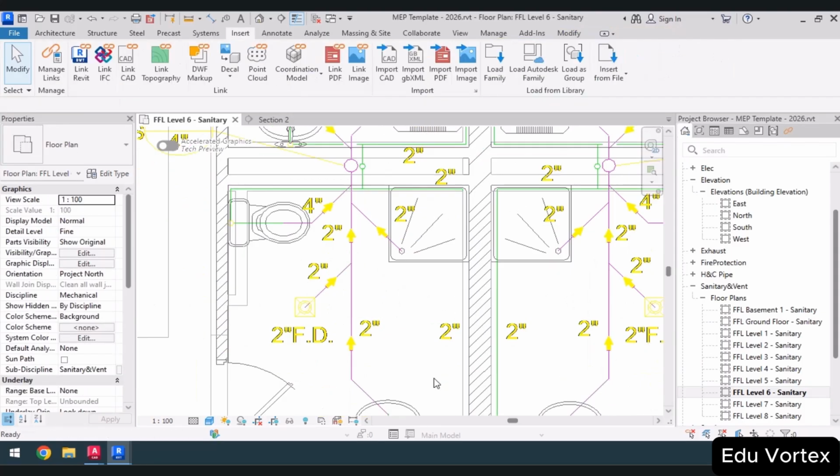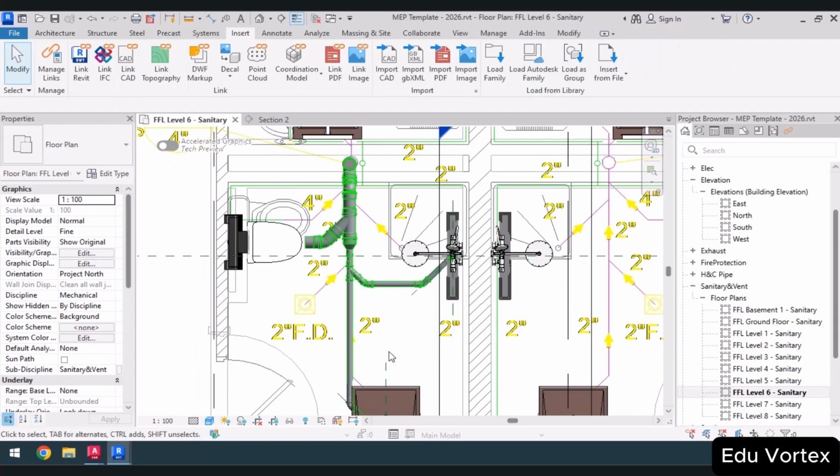So far, my overall design has taken shape based on the space required for fittings and the architectural layout of the fixtures. I have identified the best path for modeling the wastewater system. It is essential that it connects properly to the fixture, that I consider the correct slope, and that I can accurately depict the route from the fixture to the riser. These are important points for us. The routing of the pipes may also undergo some changes compared to the modeling we have done.